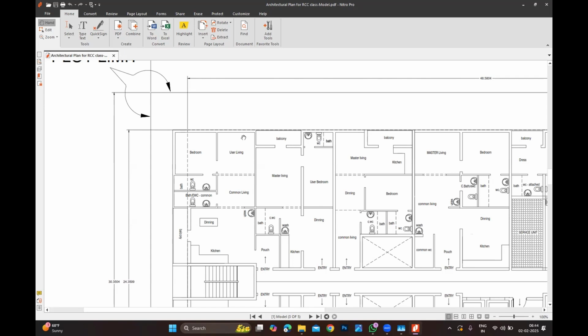Another important point: I'm not sure about it, but in Dubai, you can go out of the plot with permanent shoring 600 millimeters away from the top. This needs the NOC from the authority. Okay, I'm not sure about Dubai. In Dubai, for permanent shoring, you can go 600 millimeters beyond, even on the roadside. Not a problem, but you need to get the NOC to go for it.